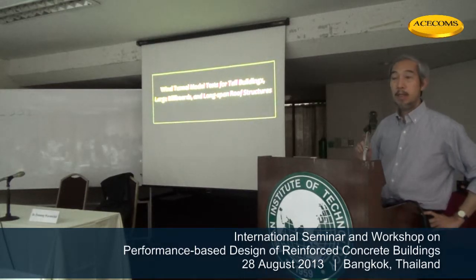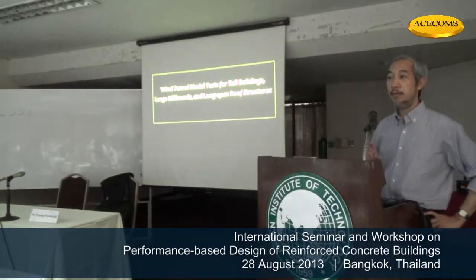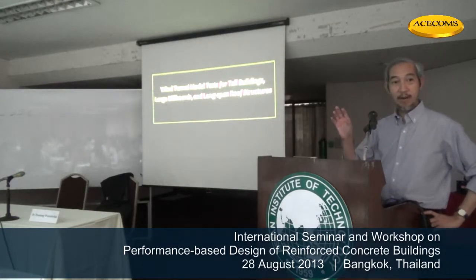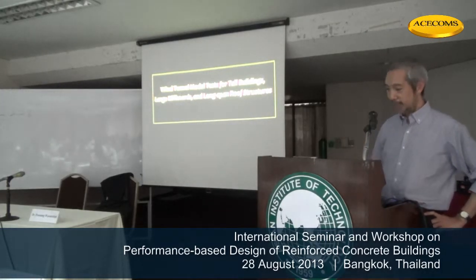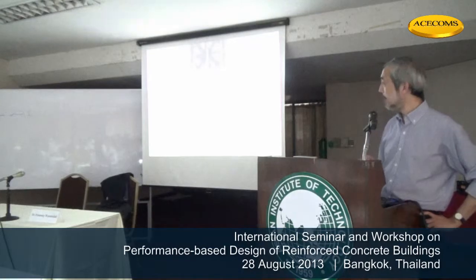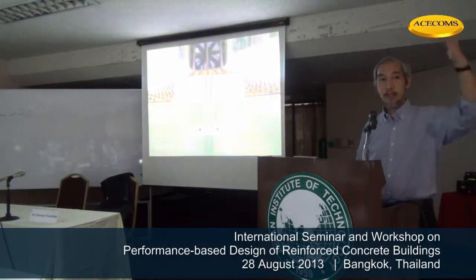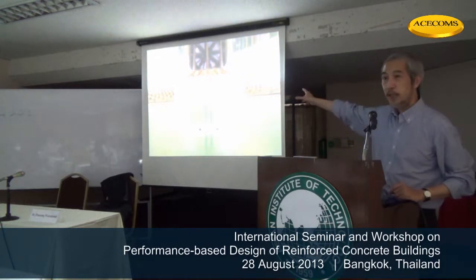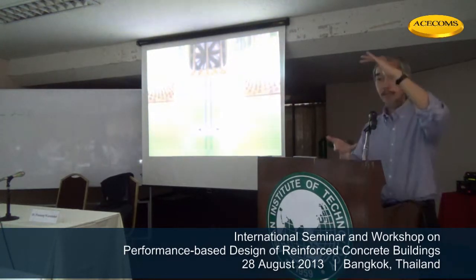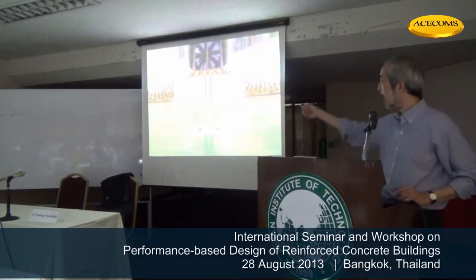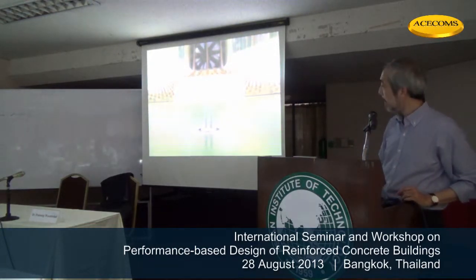Okay, the wind tunnel test is not only good for checking the dynamic stability of long-span bridges. You can do this for wind-sensitive structures like billboards. Okay, a large billboard, 40 meters high, when put in the wind tunnel, becomes this small. Okay, we can scale it down, and we put it on top of a sensor.